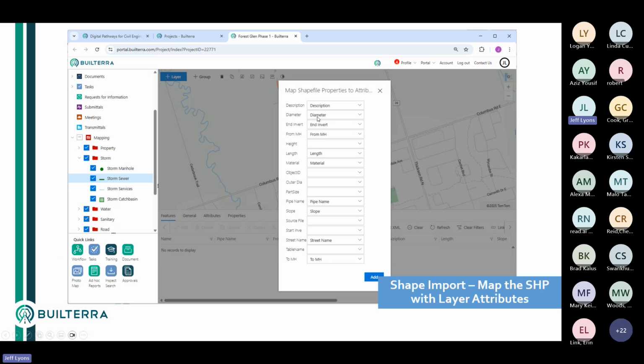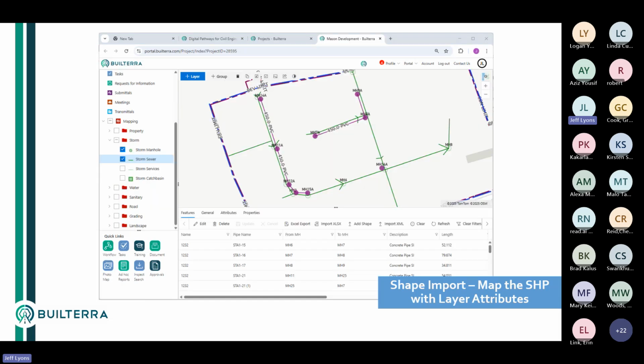So what happens here is you can map whatever's in the shapefile with the properties that you had set. Sometimes you only need half a dozen attributes, but the shapefile has 50 attributes. So you'd have to pick through. This is what I have in my table, and this is what the shapefile has here in the lookup list. And if there's a matching attribute, it'll just match it. Okay. And then when you import it, you should see the results and they should be stylized.